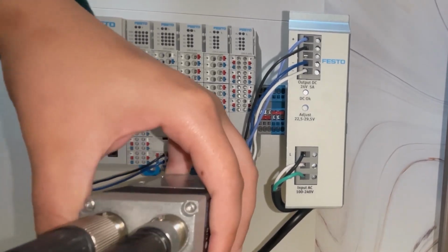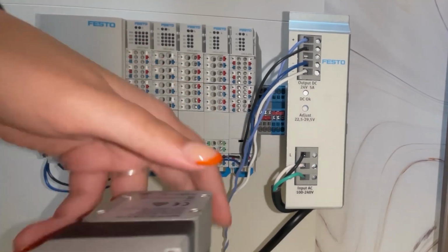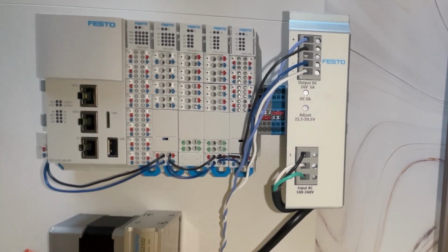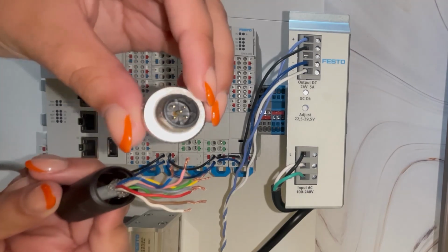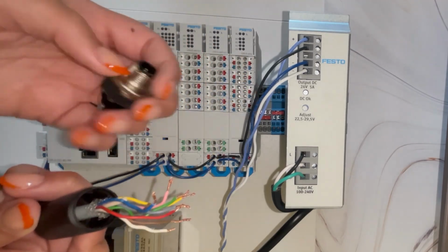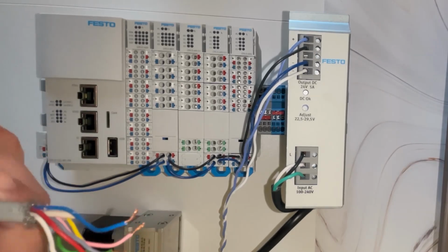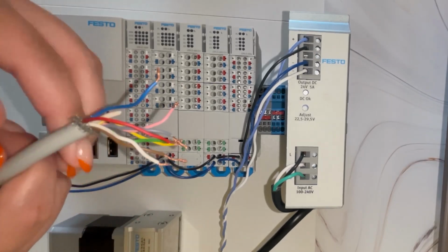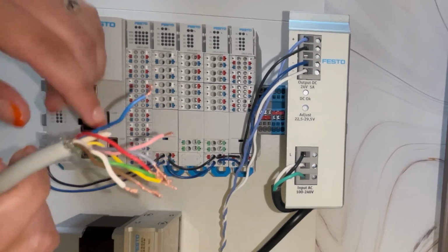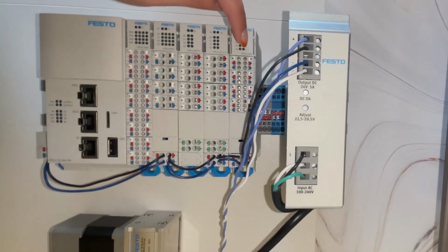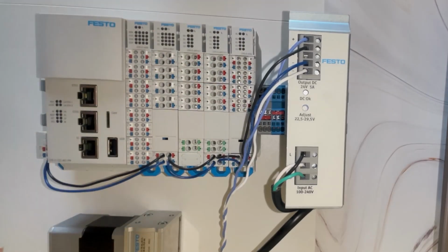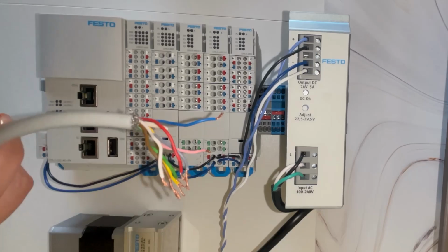Now the other connection on the SMS is the logic power connection. The other end of that cable is actually what we're going to be connecting to the PLC. So now that I've exposed the wires, it looks something like this. I basically unscrewed this so that I can expose the wires. And if you recall on the wiring diagrams from earlier, I'm going to go ahead and connect the white, green, and yellow wires to the CPXE4 IO-Link module. So I'll go ahead and make those connections now.